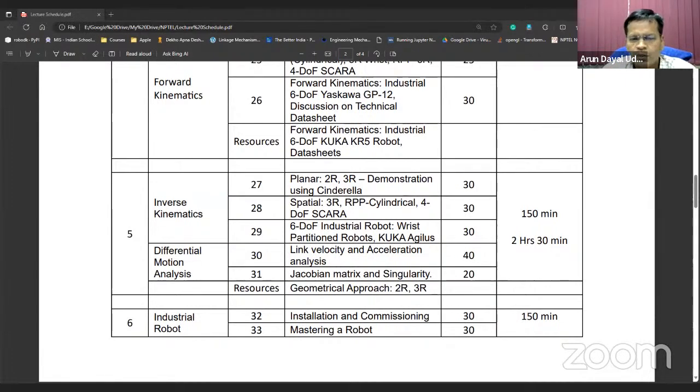You can directly do it on SolidWorks using API connectivity, using Visual Studio or those kinds of software. They allow you to connect the SolidWorks visual environment to run your code in Python or anything, and that can fetch the joint angle details to the robot in the visual environment. So there are many simulation tools, even ROS can do it. But none of them are open source in code. Coding you will have to do.